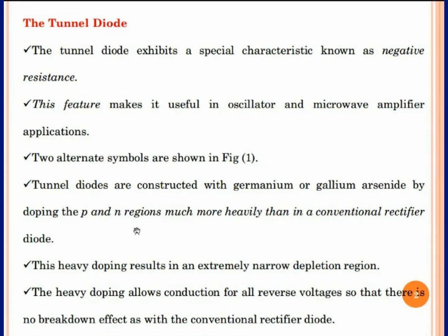conduction band. We know that whenever the electrons are present in the conduction band, only then can the transport properties happen. So for any kind of semiconductor device or any other operation, the electron should go to the conduction band to move freely. In this case, if your Fermi level is close to the conduction band, the free charge carriers can easily move to the conduction band. As a result, you will end up with more free charge carriers.